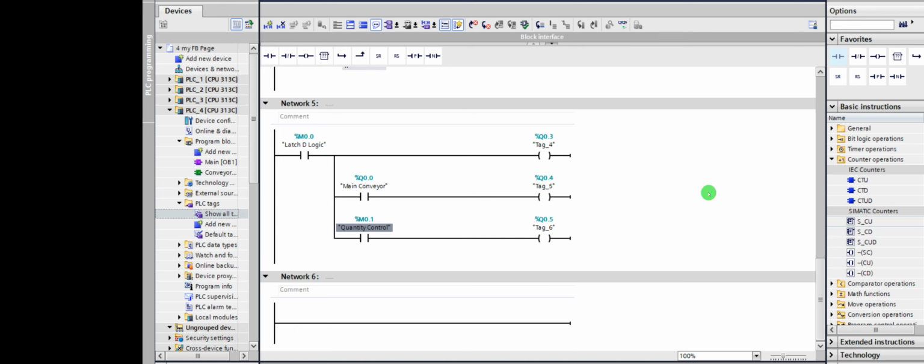Sorry, creating function, yes, function block. If you create them that way and you have an issue, you can easily come to one particular block and open it, maybe a signaling lamp block, while simulating that same logic. You come to this place only. If this one is not on, you can easily detect that the set logic network is not working. So you can easily go to the set logic network and find out why it's not working, because it's not reflecting on the indicator here. You don't need to go through the whole logic checking the fault.